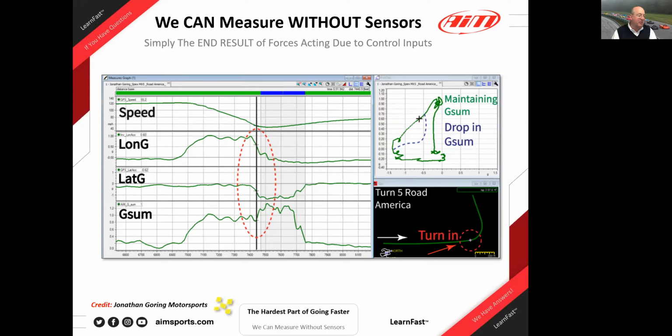I'm not going to spend a lot of time on that, but Kent, just because you can achieve that longitudinal G doesn't necessarily mean you should. So in a B spec car or a very low powered car, it doesn't necessarily mean you should go to threshold braking, but you need to know it is there, because you need to be able to compress the braking zone, and you need your braking zone to be consistently the same length as long as the braking system is functioning at high efficiency. That's the number one thing.